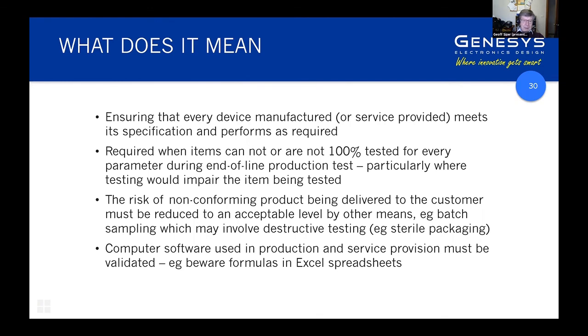And you may then back that up in manufacturing by doing a batch sampling, an AQL type process where you maybe take 5% of units off every batch, and then if no more than one of those fails, you say it's okay, or whatever your AQL level is.